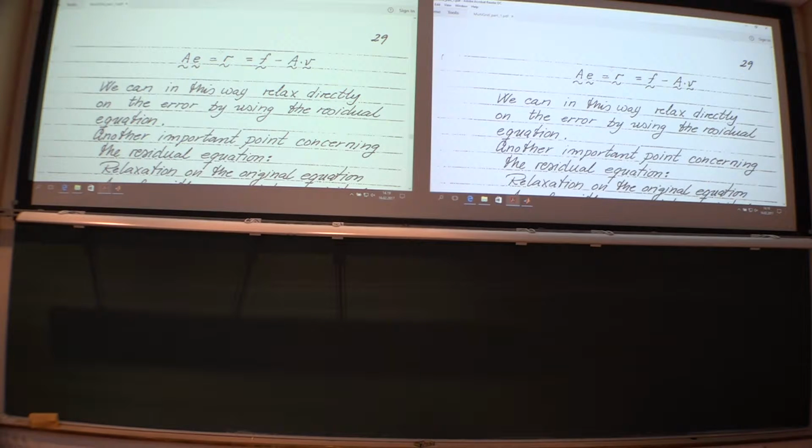And then this residual is going to turn out to be the right-hand side of the residual equation, where we are seeking now the error. But that is going to take place on the coarse mesh system. Finding the error, we then go back to the fine mesh solution that we had and adjust it, hopefully getting this one closer to the little u, the correct numerical solution.